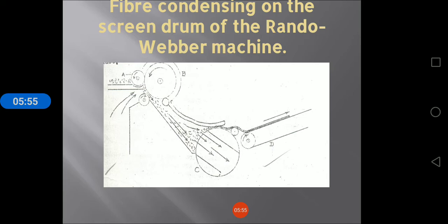In this, A is called a conveyor belt, and these rollers are called the feeding rollers of the fibers, and B is a cylinder in the opposite direction to the feed rollers. The feeding involves a beating action, opening and cleaning. After that, on the Rando Webber screen drum the web is formed. After that, the thin layer of the web is formed onto the take-up roller.